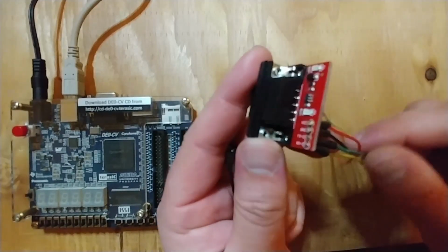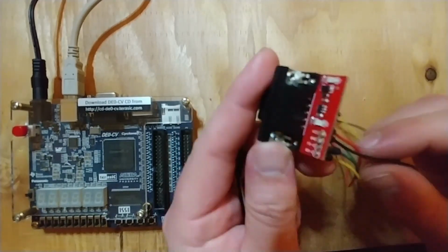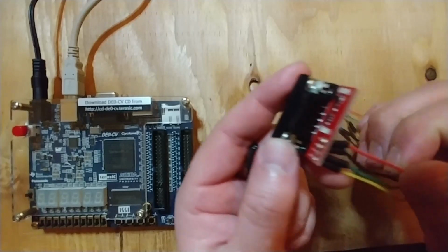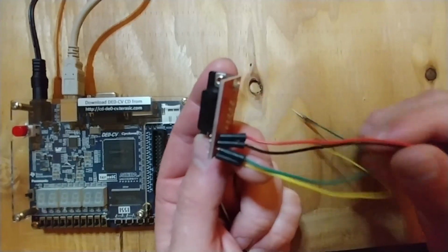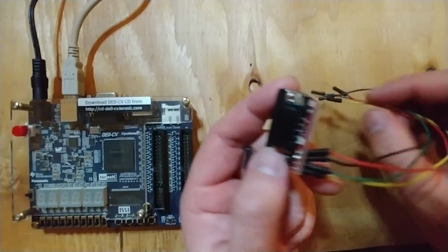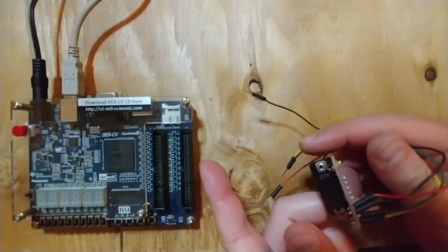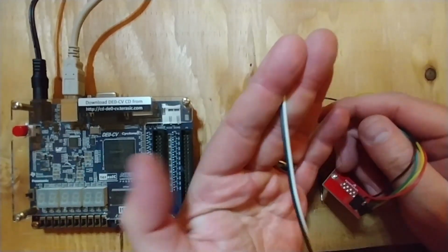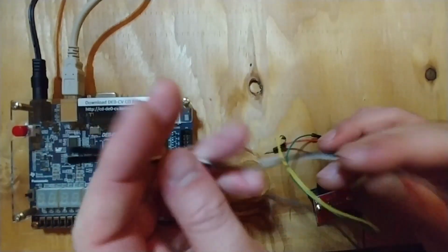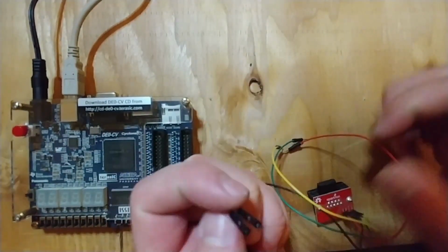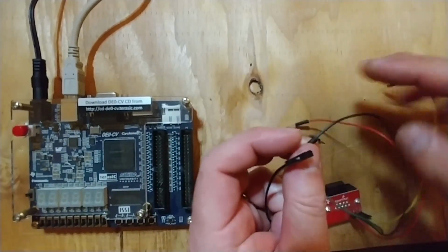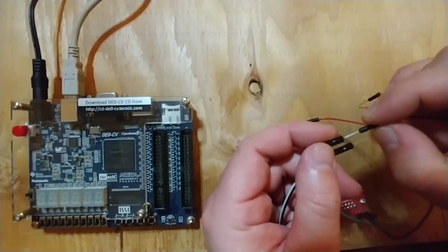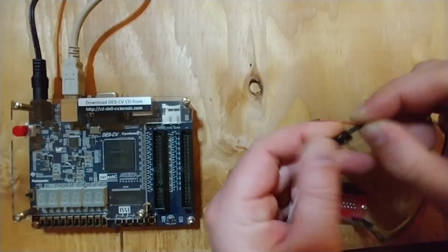So right now, first things first, I'm just going to hook up VCC and ground. VCC here is the red wire, and ground is the black wire. They all have these male connectors, but I've got male connectors on the FPGA. So I got this little female to female jumper cable. I'm going to connect black to black to keep that consistent, and then white to red because I don't really have my choice with the colors.